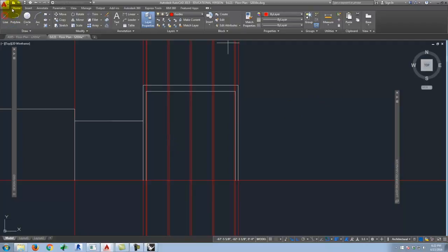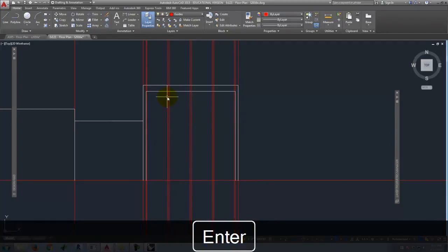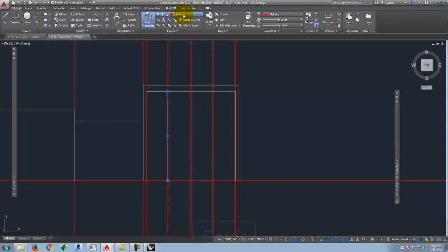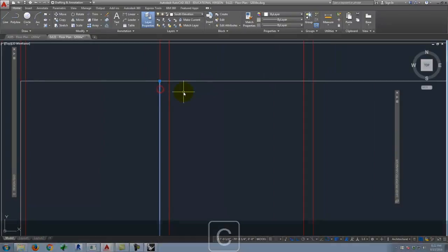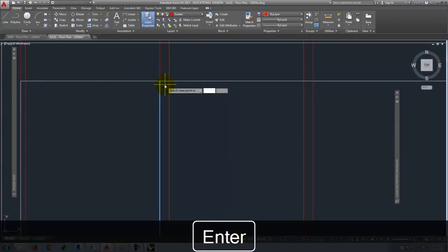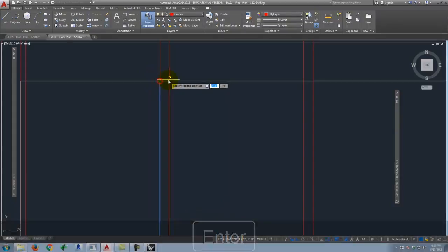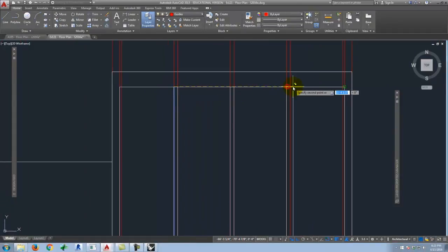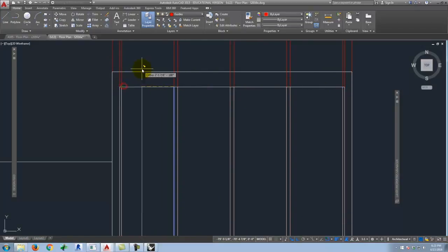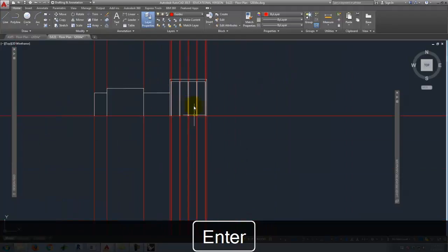And I'll go ahead and use my line tool, and I'll go right up there. Oops. Again, I didn't change my layer, so let's go ahead and change that after the fact to be my south elevation. And then I'm just going to go ahead and copy this. It's the same line all the way across, so it'll save a few more steps to just run across and make my copies. So I've gone ahead and I've drawn those.